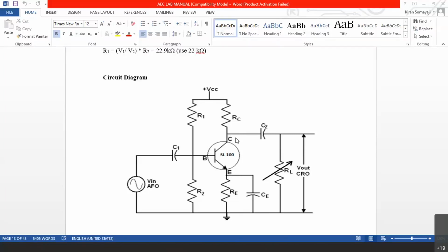Transistor is completely off means you have to check the connections at the base. Whether your R1 is properly connected to the base, R2 is properly connected, whether ground is connected, supply connected, you'll have to check all these connections again, because the transistor is not on. So you will have to verify all these connections thoroughly, only then switch on the power supply. After switching on the power supply, you should verify that the collector is at plus 6 volts. Only after that, you connect the signal generator, switch it on and give the AC signal here.